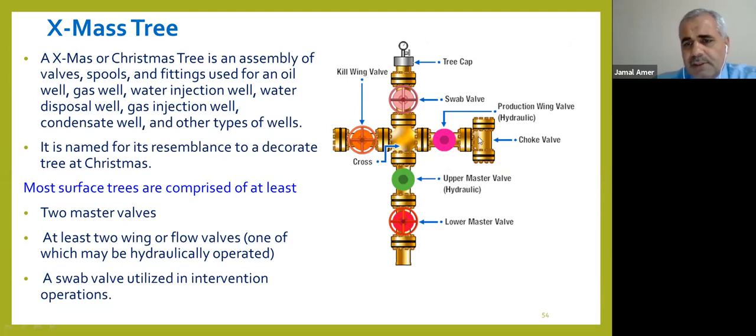Or in reverse, if it's required to reduce the production, we also need to shut down the well, open the flange from here, and replace the internal part of the choke. If the choke is adjustable, we can change it immediately. The adjustable choke can be adjusted by hand or remotely. In some wells, the choke valve can be operated remotely.